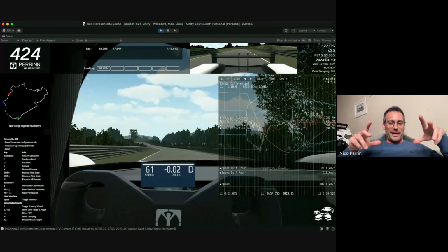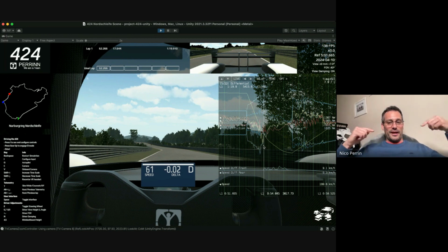But Damien complained that the car was different on their braking. I just realized I had forgotten that what I had changed as well is the amount of locking in the diff, because the regen being lower means there is less connection in the diff, and the diff will open faster. So it's something I'll have to look back at again. That's interesting, that I just remembered as we were looking at this.